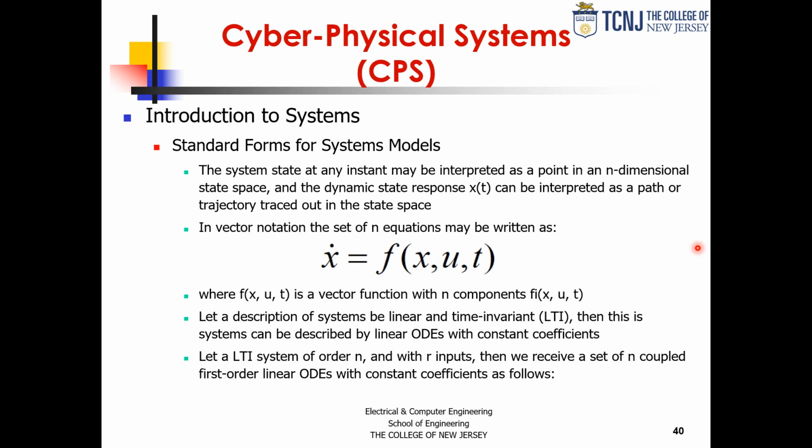So essentially we have this derivative equation, which is a function of the state, the input, and time, and it forms a vector. And as I advance time, I can see a trajectory through time, but in the state space. Well, again, that's harder to visualize if you are not doing op-amp based compensators for control systems, which nobody does. But I think where you can see that is in state machine design.